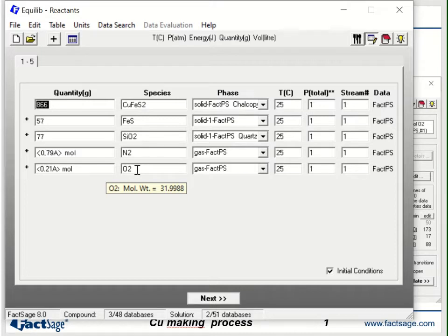But if you want to see the energy difference between the initial state and the final state, the initial mineral phase is very important. Depending on the phase, you have a different amount of energy assigned for the phase. So if you want to use the initial condition like this, and you want to really calculate the energy change between input and output, then you had better use the actual species, with each phase and the initial temperature simultaneously, to get a more accurate energy balance calculation.